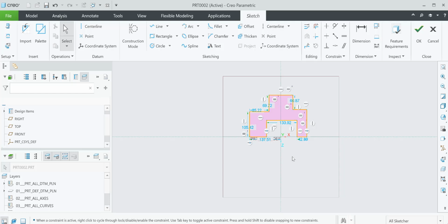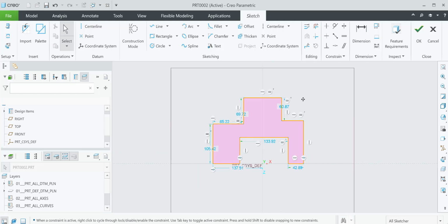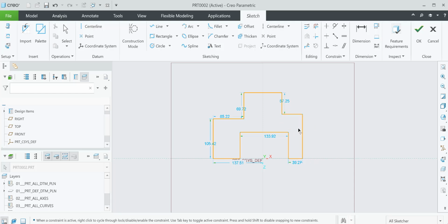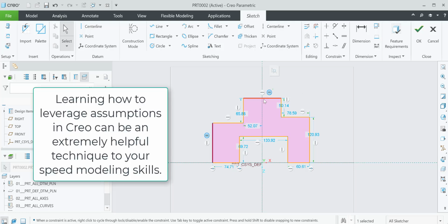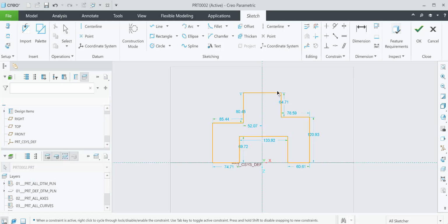Alright, I hit the middle button when I'm done, and the geometry color's pink. If I drag a sketch around, you start to understand that the equals aren't working for my strategic advantage. So I deleted the equals, hitting the delete key on the keyboard. Those are established on the fly. We call it an assumption. If you don't want this leg to equal that leg, you click the icon and hit delete. Most CAD packages are like that.